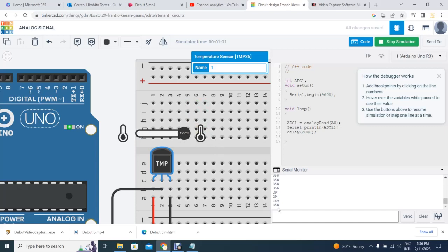When I move to 125, you can see that the range of the instrument in ADC is from 20 to 358. How about if I put it somewhere here? Well, how about 105? If this is a linear curve, then this 319 should be within the line of the calibration, hopefully, because again, if this instrument is linear, we should have a linear result. Now, how are we going to do this? Very simple. This is the part that is done by hand.